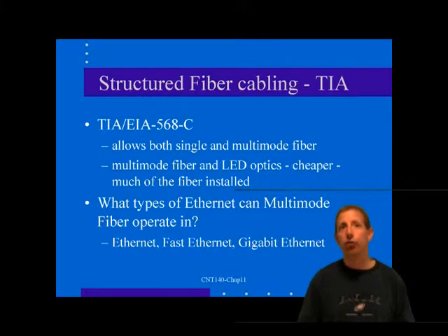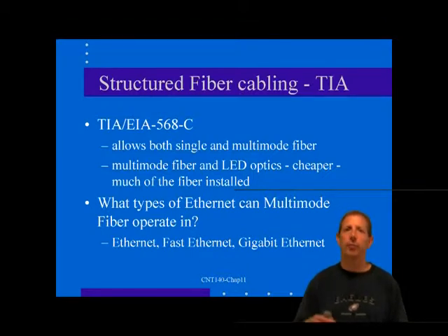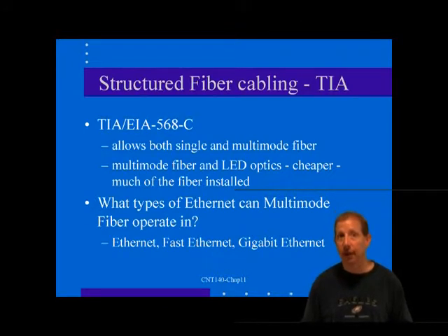The tried and true method of fiber connection is the structured cabling systems conceptualized in the 568C. And as you recall, this standard allows for both single mode and multi-mode fiber. Although the earlier A version really encouraged the use of multi-mode in the horizontal structure, the single mode is in the backbone.